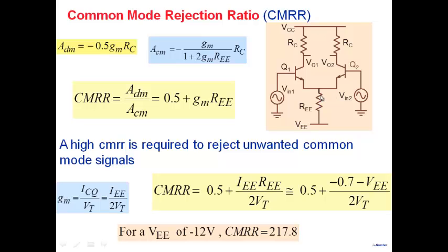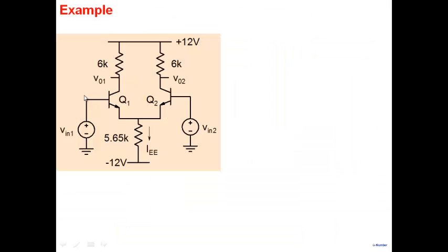Once we take this out and replace it by a transistor, we'll see that you'll be able to get large CMRR, and the CMRR would then no longer depend on the supply voltage. You can get high CMRR even though you have supply voltages of plus 1.5 or minus 1.5. So we'll see that later on. That's how we'll try to improve CMRR, by taking RE out and replacing it by a current source, a transistor. All right, so that's for later on.